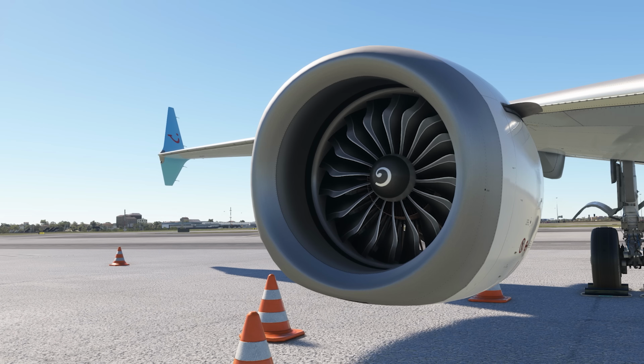Now, as I mentioned briefly at the start of this guide, the pitch setting for most phases of flight is exactly the same, but because of the size of these engines, the N1 has changed for most phases of flight. What you'll find when you're flying this in Microsoft Flight Simulator is that the thrust setting for most phases of flight is around 7 to 8% less. So for example, when we're level at around 3,000 feet maintaining 220 knots in the NG, you needed about 55-60% depending on your gross weight. You'll find with the MAX you need around 48 to 52% approximately to maintain that same speed.